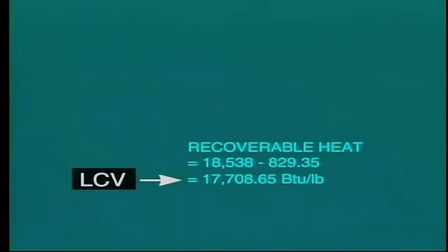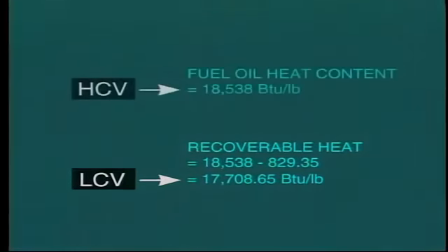This value is actually known as the lower calorific value, indicated as LCV. The higher number that we quoted earlier is known as the HCV, higher calorific value. When comparing fuels and looking at the efficiency, it's essential that we make ourselves aware of exactly which value for heat content is being quoted.